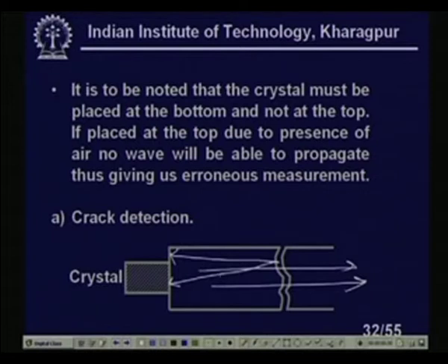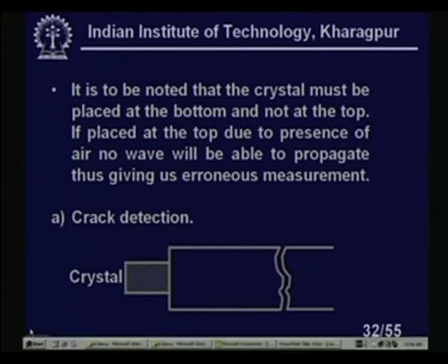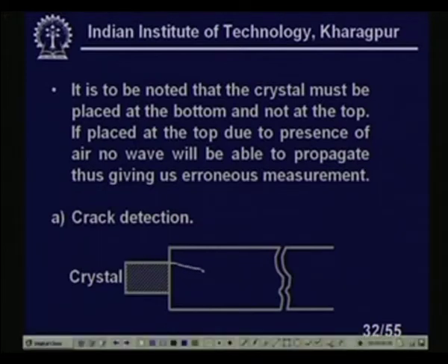If I know the time, if I take it, what will happen? It will go, it cannot move through air, so it will reflect back. So, if I measure the time, I can exactly locate where the crack is, even though from outside it might be invisible if the crack is inside, right. This is a very excellent technique.